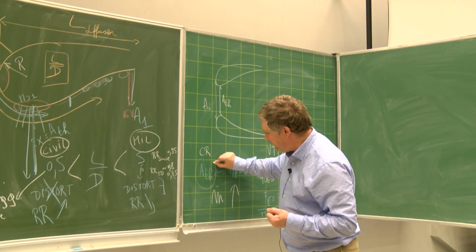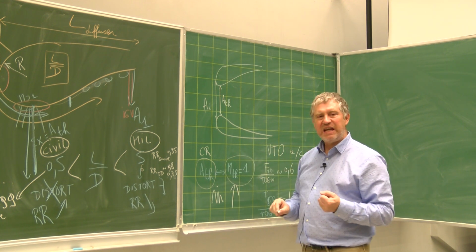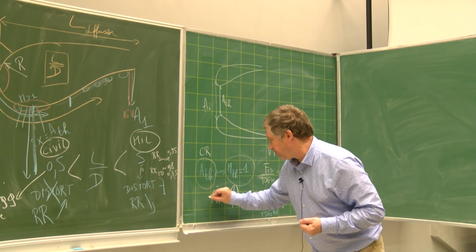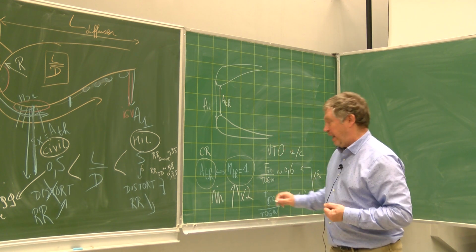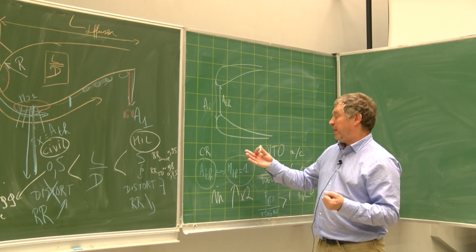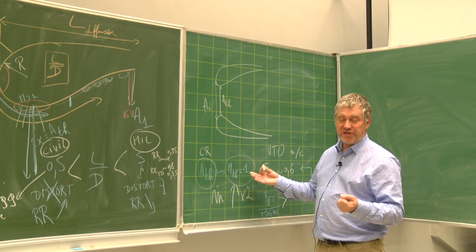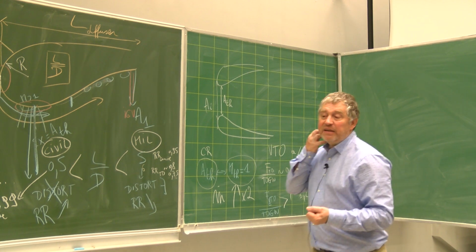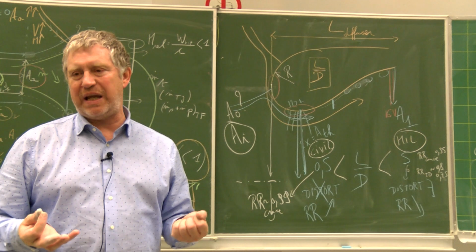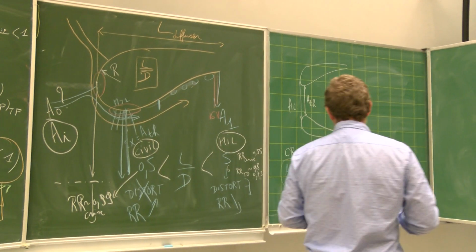The danger would be that in the A throat, you could reach M throat equal to 1, because you need to increase the m dot by a factor 2. And increasing the m dot by a factor 2 means you increase the throat Mach number by a factor 2, and then you could reach indeed 1. And that's what we call choking of the intake. Choking of the intake. And how will we solve that?